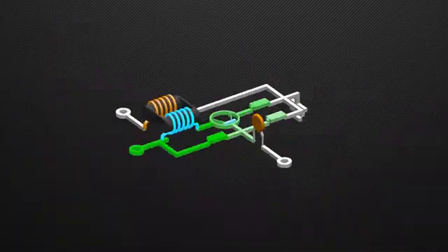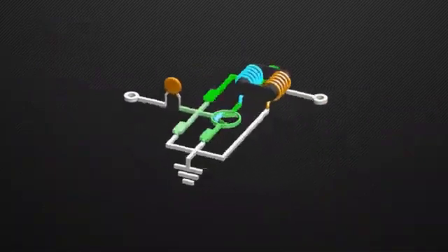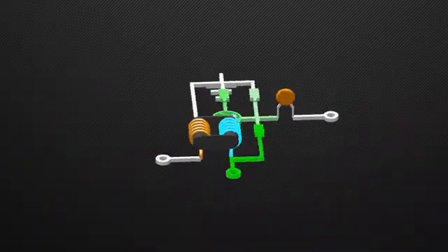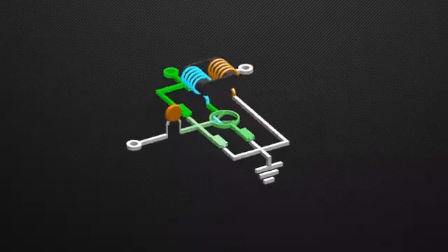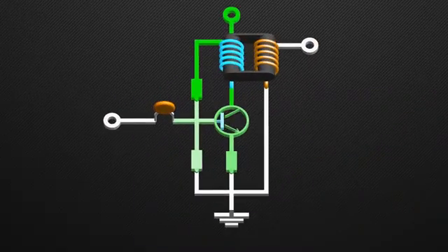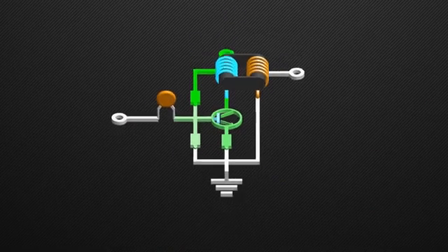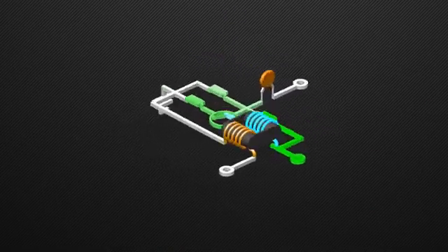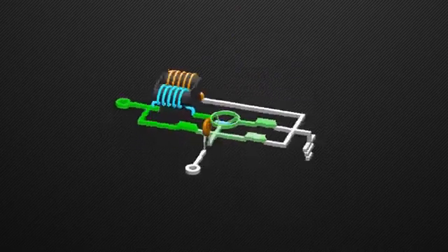This circuit has a transformer, in place of RC, to increase the efficiency of the circuit. However, the transformer is an inductive device due to its windings and core, so using inductive components in amplifier switching circuits is best avoided, as any back EMFs generated may damage the transistor.